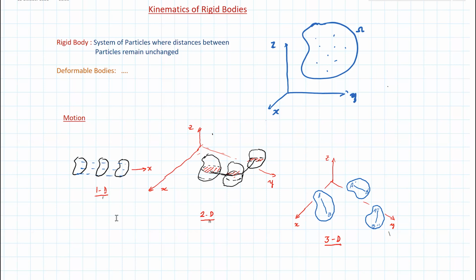So this means that any motion here of the particle is either in, say, the xy plane or any plane parallel to this. It is like slices. You assume that you cut the body in horizontal planes, and every particle will move in its own horizontal plane. So that way, what we require here is only the analysis of 2D motion.